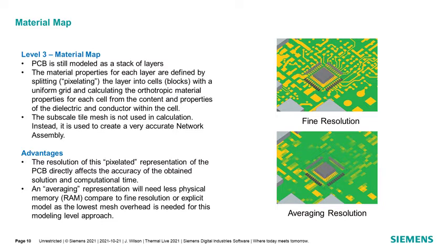The process would be to subdivide the PCB into a number of patches. So you could think of a black and white image. If you were to pixelate that, you would get some pixels or blocks or patches that are white, some are black, and many that are different shades of gray. And that's essentially what this process does, it pixelates the image of the copper to the resolution specified. There are 2 basic approaches or controls to implement this.